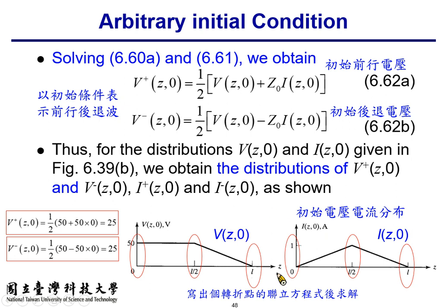And another thing that you need to be careful about is the boundary condition. You see, the current distributions are 0 on both ends. This is the result of the boundary condition, which are open terminations. Because at the open termination, the current must be 0. For short termination, what is the boundary condition? The voltage must be zero on short termination, and the current must be 0 at open terminations. So here we see because they are open terminated, the voltage on the ends can be either 0 or 50 or any other values, but the total current must be 0 at the termination.